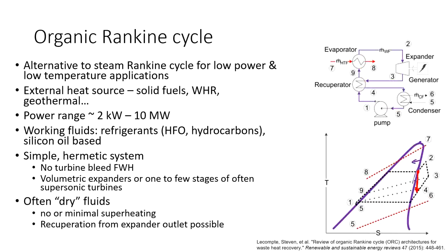So these cycles typically don't need very large superheating, typically just few kelvins in order to make sure that the working fluid entering the turbine or expander is dry, that there are no liquid droplets.